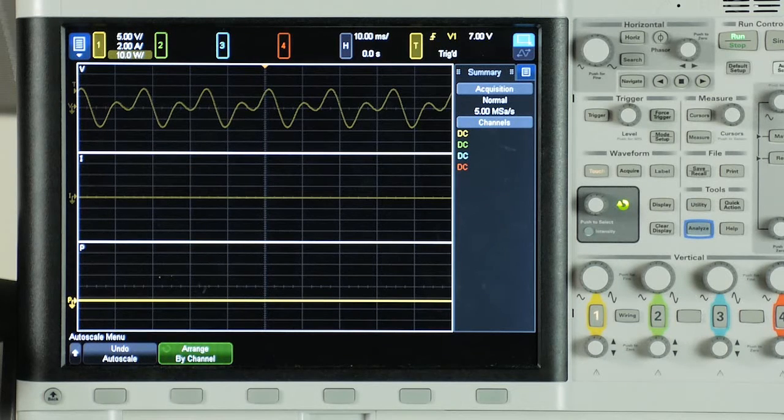One way to do that is we have a function generator that can output a signal at the fundamental frequency of 60 hertz, and then I'm going to sum an additional signal that's modulated at a different frequency, some multiple of 60 hertz. So in this case, I'll feed in a 60 hertz signal, and then I'll sum it and modulate it with a 120 hertz signal with full modulation. When we look at the magnitude bars, we will see full magnitude at the first harmonic, the fundamental, and then at the next harmonic we'll see the same amplitude because it's 100% sum frequency.